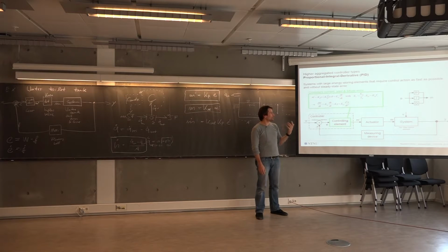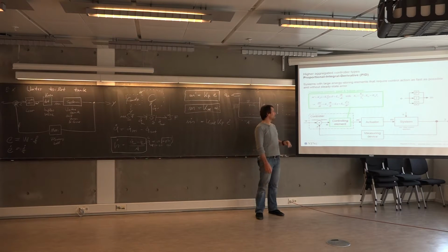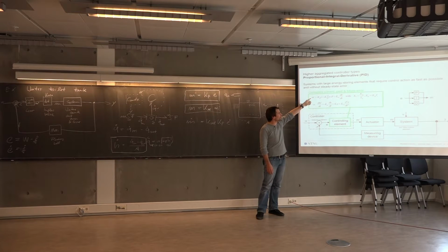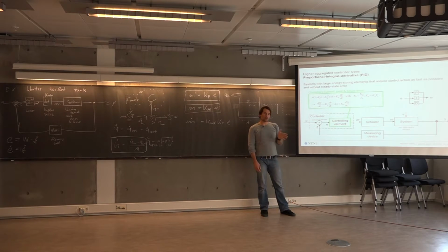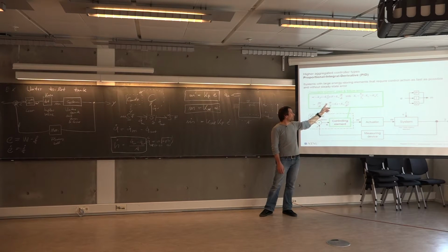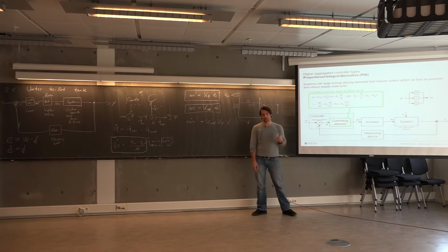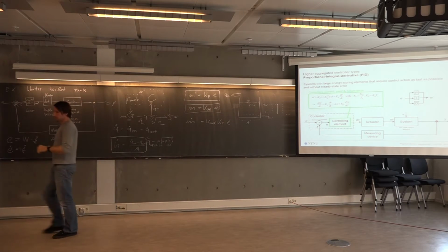And as previously mentioned, in order to use that in the function file in a more or less nice way, we take the derivative of this equation, and then we end up with the second equation, which again has three terms representing proportional, integral, and derivative control, but now with the respective derivative of the error variable in each term.